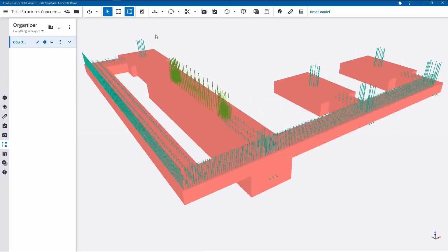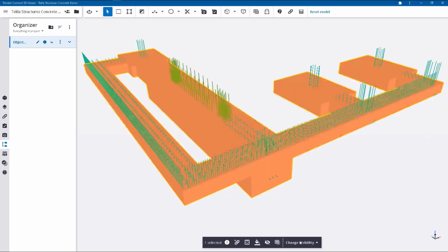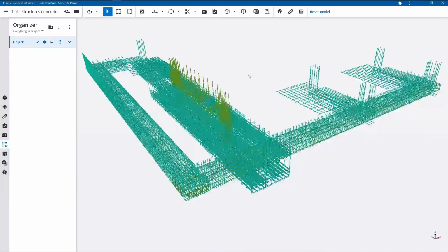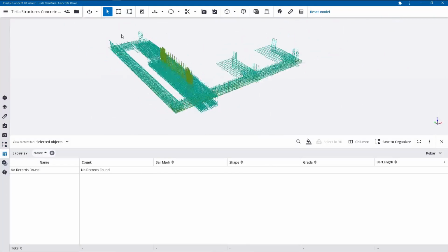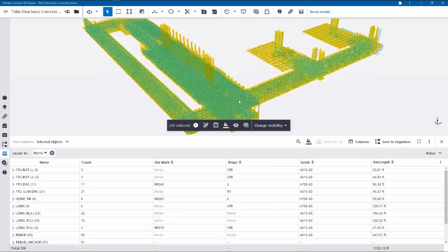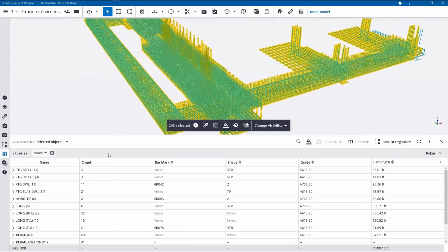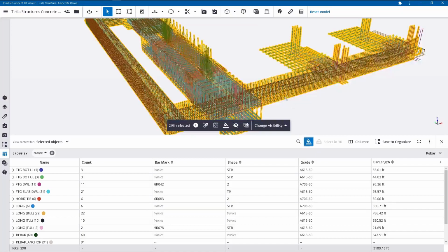then viewed its properties in the object browser down at the bottom portion of the screen. But with the organizer categories on the left-hand side, we can actually go ahead and make selection of objects that much easier. To do so, we'll go back to our property browser and then start selecting our entire reinforcement again. From here, we can also color code our reinforcement based off of the grouping that we have here by name. It's really easy to do so.